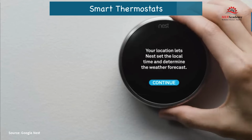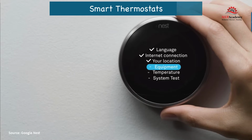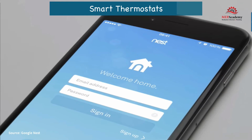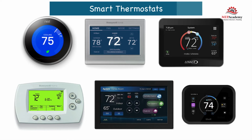When a thermostat sends a signal to the furnace to provide heat, the combustion air fan will start to ensure proper air for the combustion of the gas. Then, to confirm that the combustion fan is running, there is some form of pressure switch that picks up pressure created by the fan, which then energizes the hot surface igniter. After a preset time, the hot surface igniter will allow gas to flow to the burners. After another preset time that the burners are operating, the blower fan will start and blow air out of the furnace into the space. If the system fails to light the burners after various attempts, it then shuts off the system and you should contact a service company to determine why.